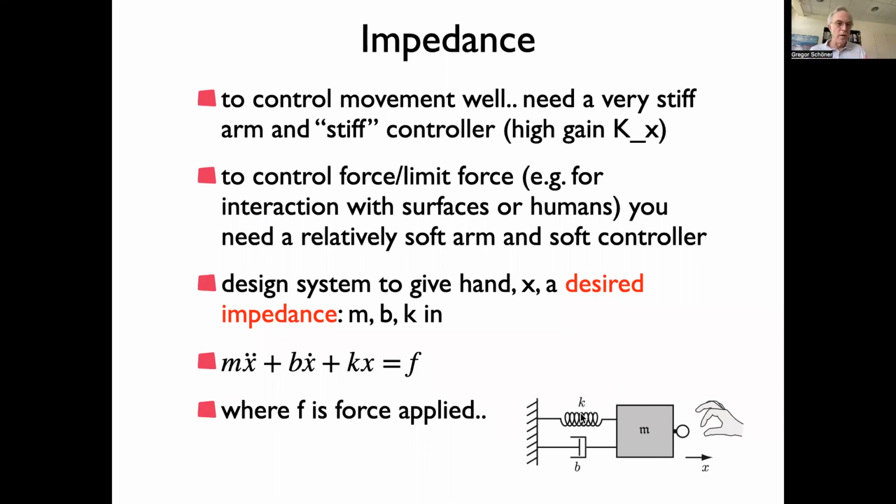The force will grow slowly as my distance varies. On the other hand, when I'm hammering, or digging a hole, you might say I apply much higher forces, but what you're really doing is that your position control is very stiff, so that as you dig into the material, you ramp up your force quite a lot. And that's something we humans do all the time. Well, in robotics, it's only a very special branch.